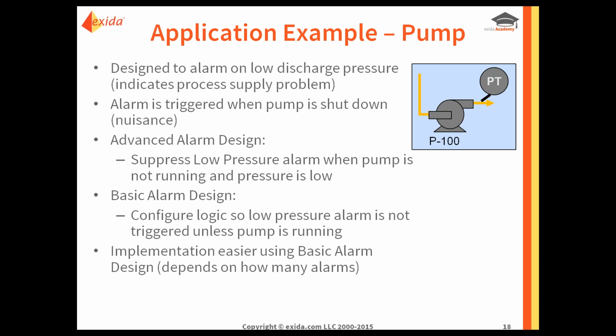We're going to look not only at the value of the pressure itself to see that it's low, but also at the run status of the pump, and combine those two, and only generate the alarm when those two conditions are met, when the pump is running and the pressure is low.